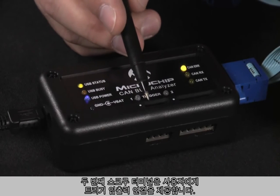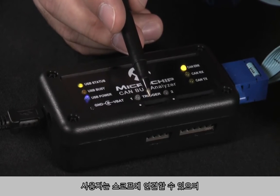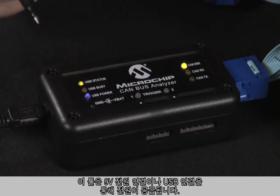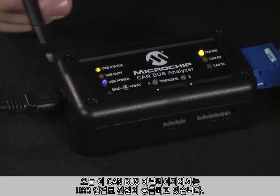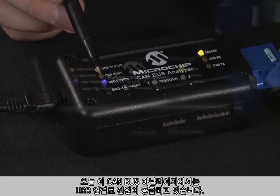The second screw terminal provides the user with trigger input and output connections. This allows the user to connect to a scope, and when a certain CAN message is received on the bus, the analyzer will then trigger the scope with a pulse. The tool can also be powered through a 9-volt connection or USB connection. In this setup here, the CAN BUS analyzer is powered by the USB.